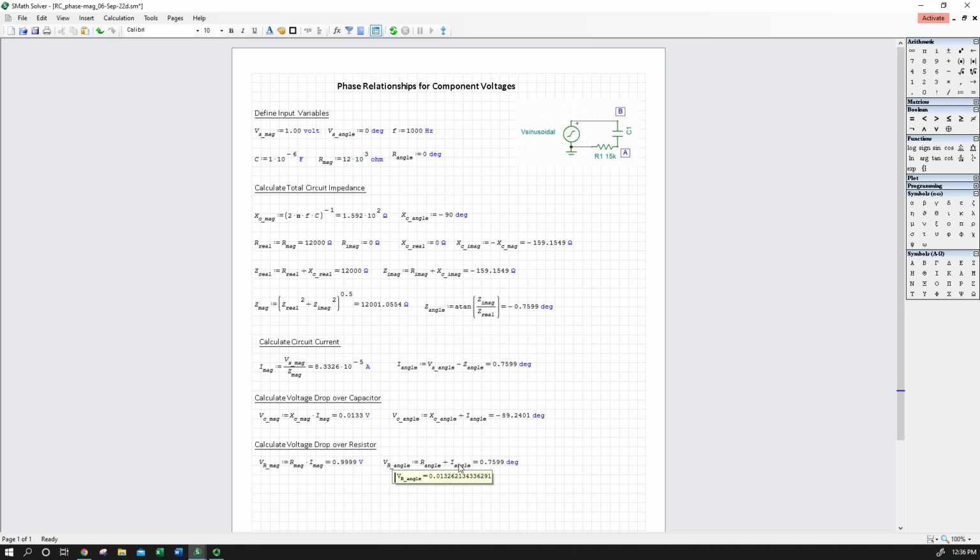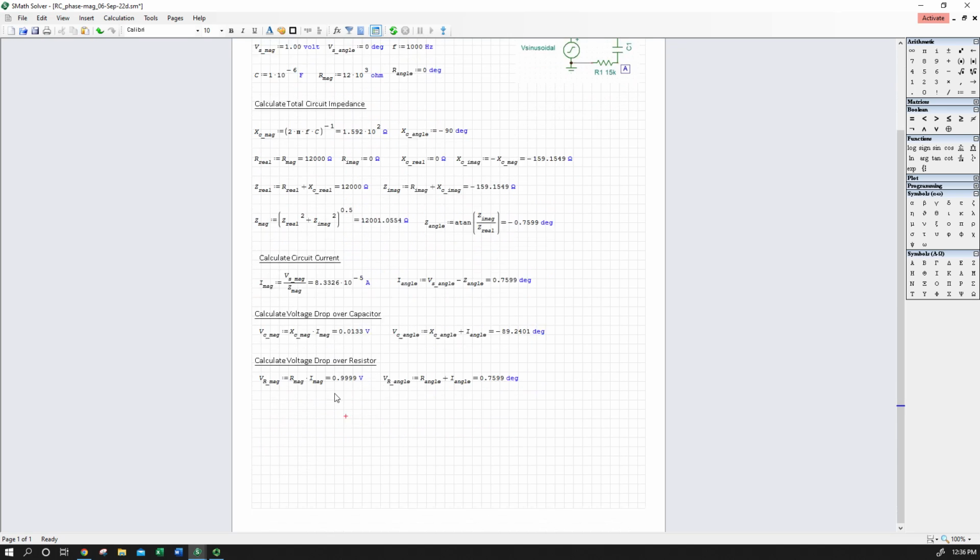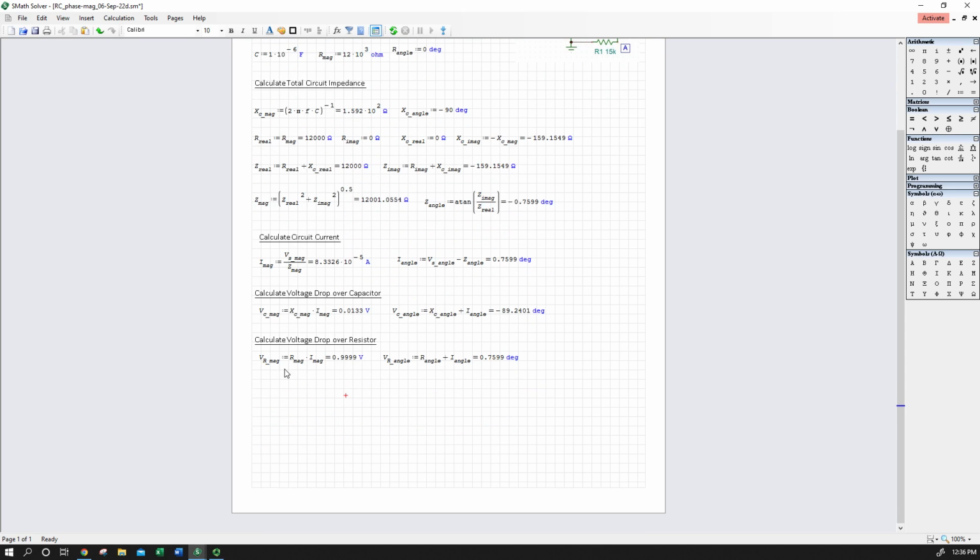And that's how we can use the voltage drop over a pure resistor to actually measure the angle of our current. We're going to use this very relationship. So, kind of like using a shunt resistor to get the magnitude of a current, we can use this 0 phase angle relationship of the impedance of pure resistance as a great way to get at what my current is doing when I can only measure voltage. No problem. We get that 0 degree phase angle.